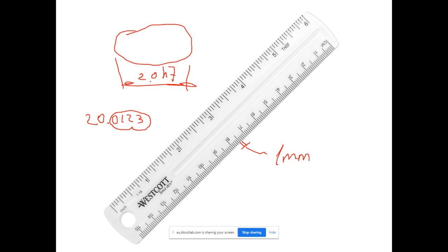Now, the upper limit or lower limit, and also you know the definition, upper limit UL is equal to nominal value. Nominal value is the dimension that has been shown on the technical drawing, plus upper deviation. I always write the expression of this equality saying plus. If the deviation is negative, then it is going to be subtraction. From here, deviation means upper limit minus nominal value.